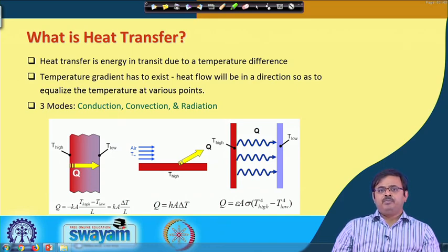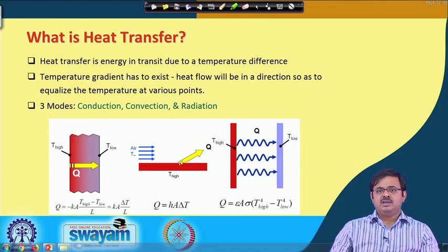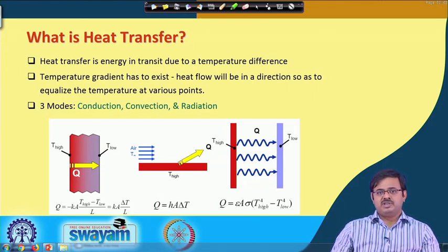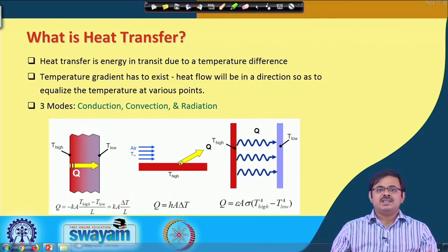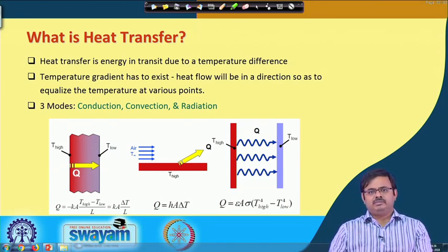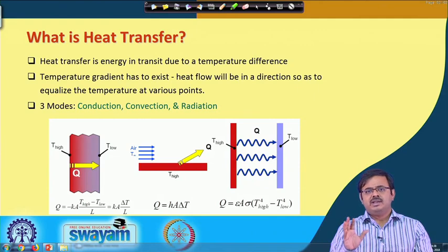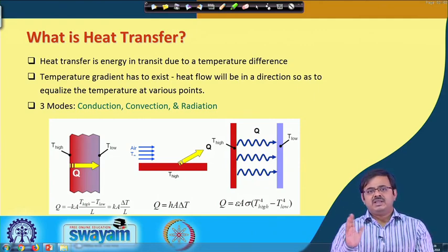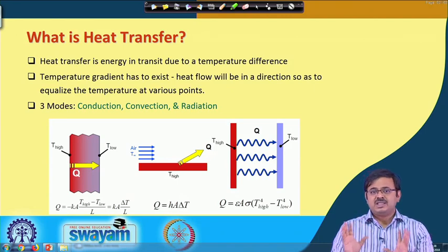Okay. So, the emissivity of a surface typically is a function of the wavelength, but sometimes what we do is we plot emissivity as a function of wavelength and give it an average value and call it the gray body approximation, and we say okay, this surface is a gray body with emissivity of 0.7. Okay. So, 0.7 is actually a mean value, and it helps us in calculations, that is it. Okay. So, I think I am giving a little more detail than required, but what I am trying to do here is give you a recap of the basic modes of heat transfer, because this is very important.